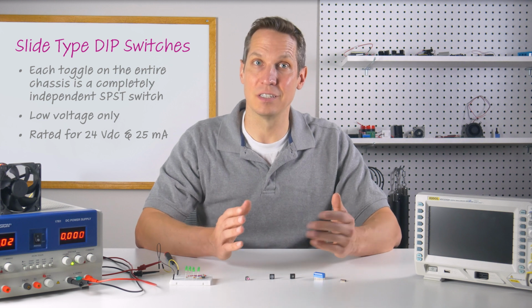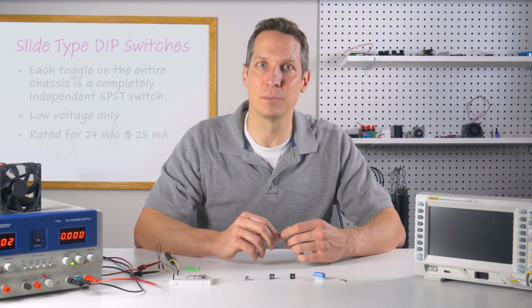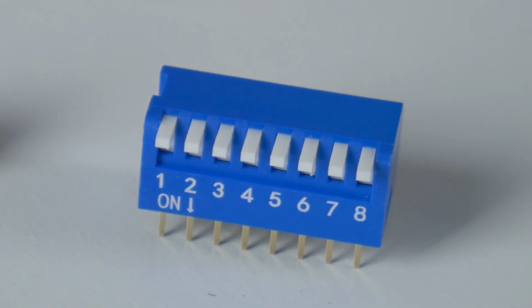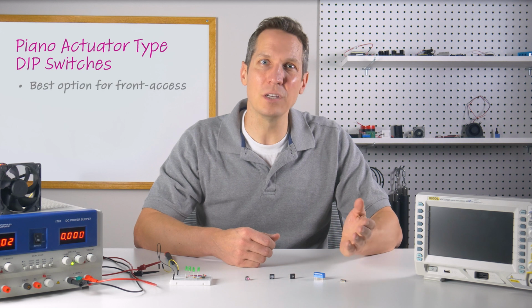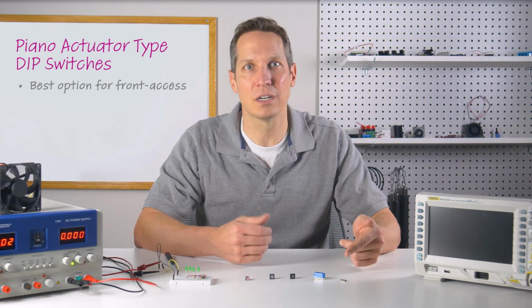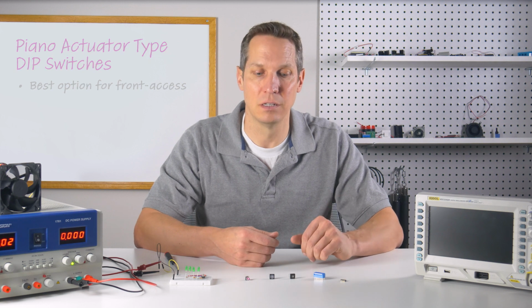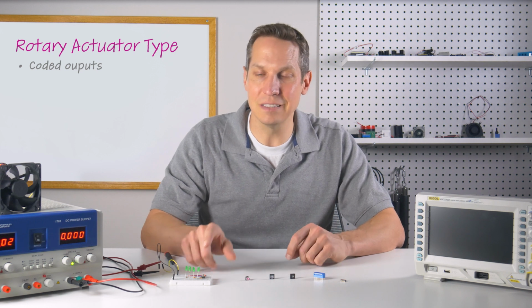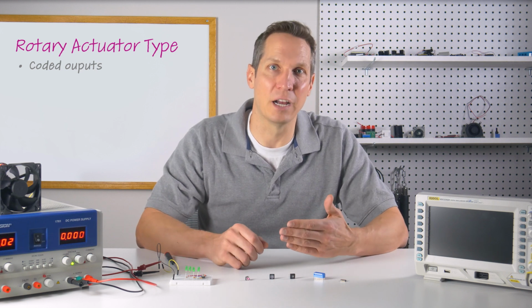Very similar in function to the slide actuator, but slightly easier to change position, we have the piano style, like this one. These are named due to the obvious comparison to piano keys. If the DIP switch is only going to be accessible from the front, this is a better option than the slide actuators, which are ideal for access from above. Finally, rotary actuators are unique and they usually have coded outputs. For example, this DIP switch right here has a binary output.